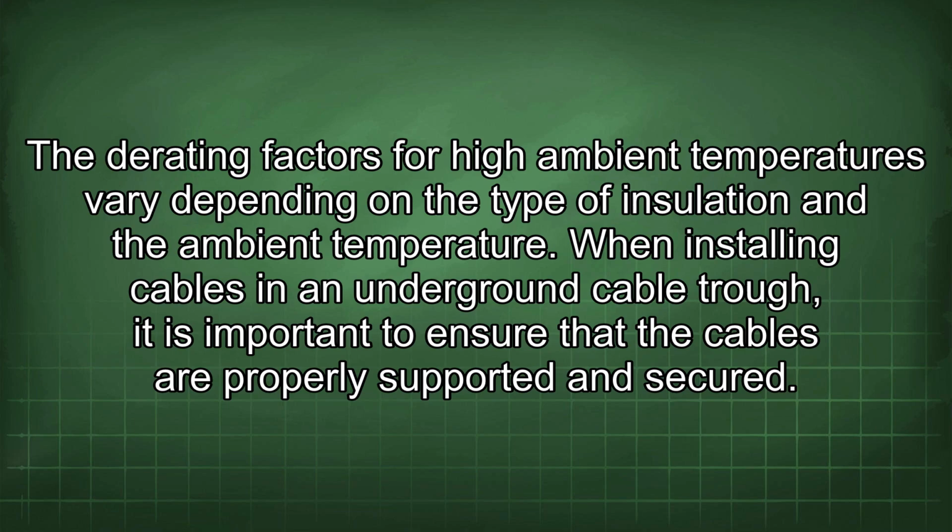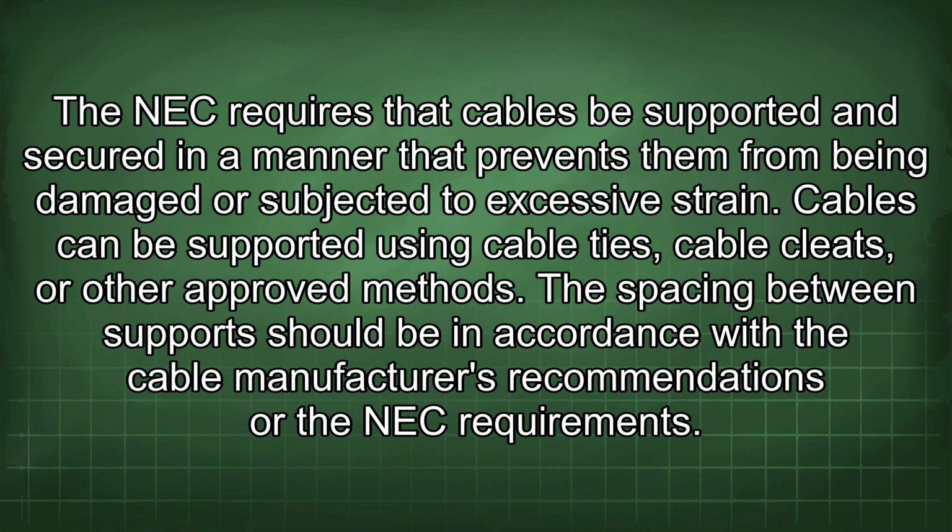When installing cables in an underground cable trough, it is important to ensure that the cables are properly supported and secured. The NEC requires that cables be supported and secured in a manner that prevents them from being damaged or subjected to excessive strain. Cables can be supported using cable ties, cable cleats, or other approved methods. The spacing between supports should be in accordance with the cable manufacturer's recommendations or the NEC requirements.